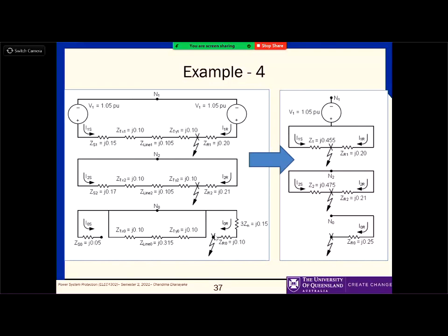See, the zero voltage, the fault occurred here. This is the generator impedance, 3 times of it, and then generator zero sequence current going to the fault. Now it is open towards the transformer. Why? Transformer is delta. But inside the transformer, the other side of the transformer is Y connected with ground. So that's why these two exist. But there is no link between this part and this part, right?